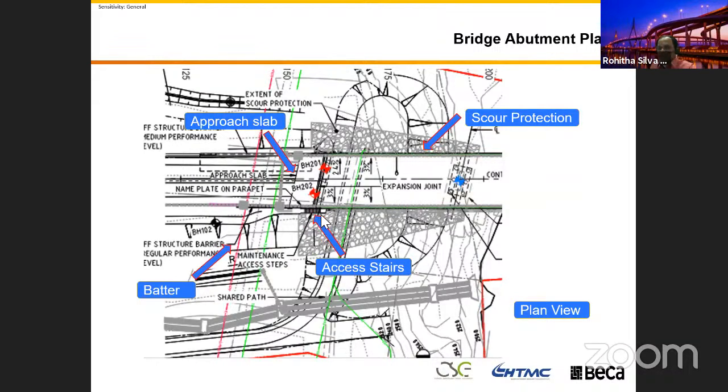And then to inspect them, and sometimes when the bridge behavior, settlement and other unexpected things happen, the bearing will walk, as we call it, and then you need to go and readjust the bearing, or else replace it. For that, the maintenance crew need to access these places, so you need to provide the access stairs and the walkways underneath to access them.